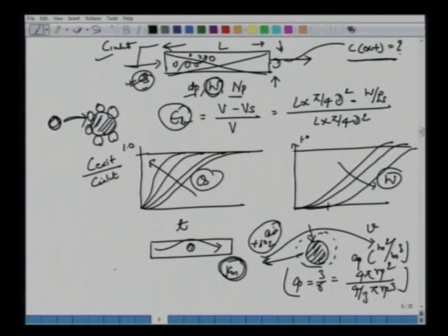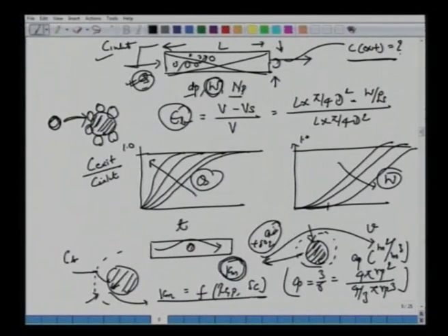Pictorially, we have the solid, non-porous with no pores inside, and a concentration profile: C bulk, which then drops because of the mass transfer resistance, given by the mass transfer coefficient, which recall is a function of the Reynolds number and Schmidt number. The first 3-4 lectures on mass transfer can again be applied here.